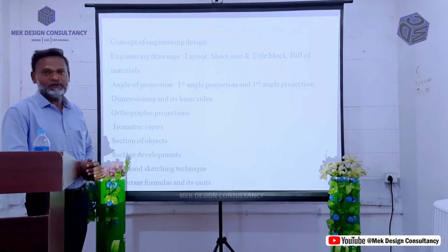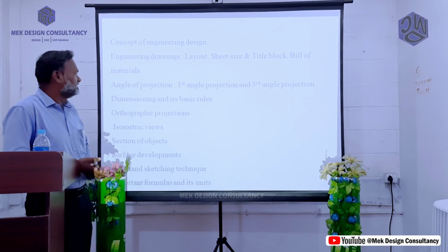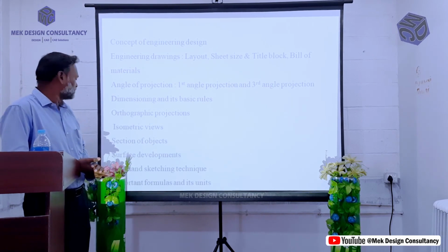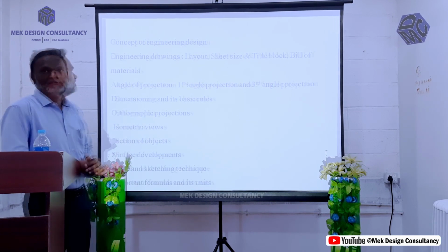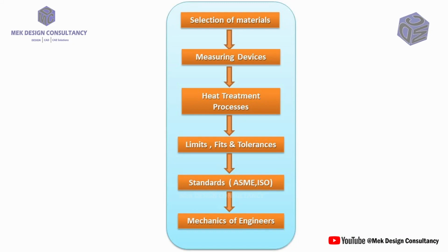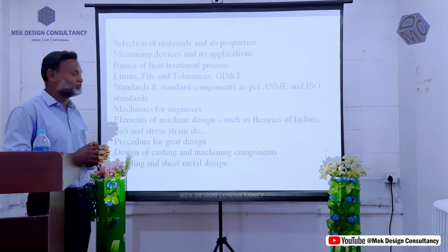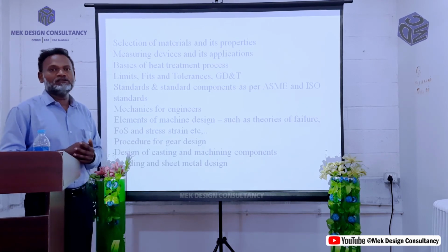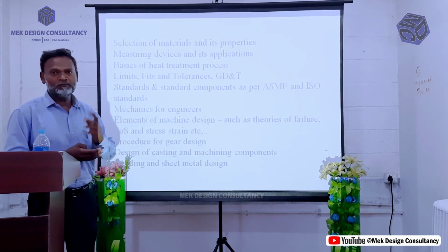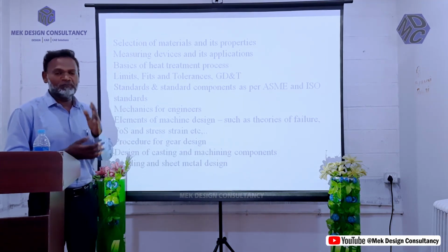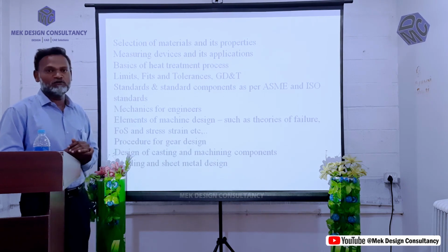There are also basic parameters like dimensions, detailings, isometric views, orthographic projections, surface development and sections of solids. We should know the selection of materials and their properties, basic heat treatment processes, standards and standard components, basic mechanics, and how to select channels and structures, and standard components like bolt, washer, nut and circlip. How we select them depends on the basic size and the pitch.